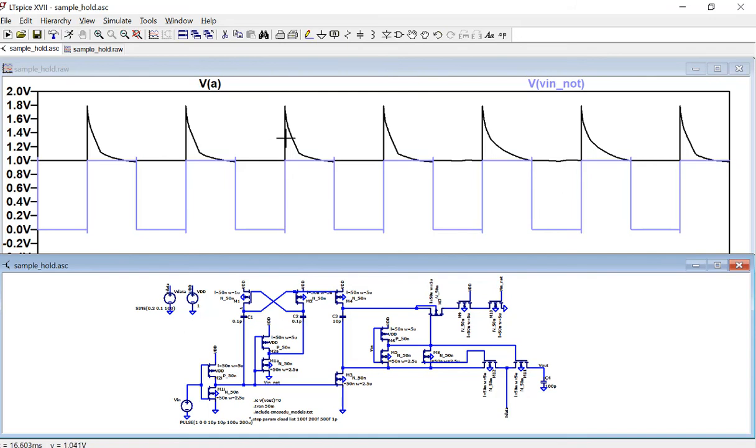Yes, so when this is going up, this is going up as well at the highest voltage. So at this rising edge, I'm able to pass the entire VDD to this point, to this capacitor. Even though it's getting lower than the highest point, that's fine because it's still higher than VDD. I'm able to provide a voltage higher than VDD for this period, so I can pass the entire VDD to the top plate of C3, and then turn it off. Just cut it so the charges will be stored in the capacitor. That making sense? So whenever the charges are ready, I can start sampling.